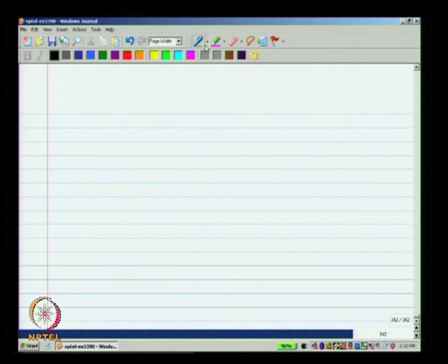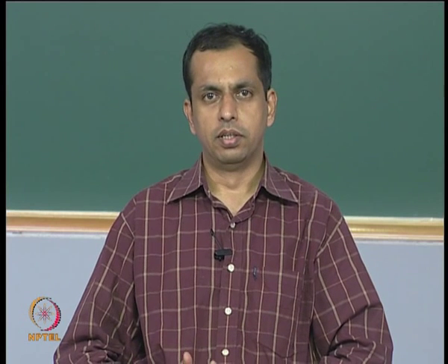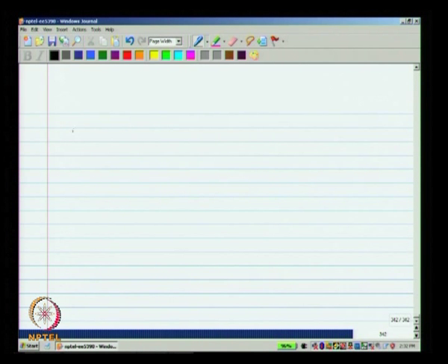Now, for this illustration I will use the common mode detector without buffer. Okay. This is because it is just more complicated to draw, but you will get the point even without the buffer. The part that I am going to draw now is the common mode detector itself plus the single stage single ended op amp used for feedback.